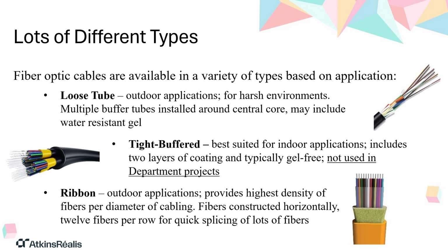Multiple buffer tubes centered around a central strength member, and some will include water resistant gel. Now, before you subscribe to the water resistant gel, check the specifications and preferences of the local maintaining agency, as some agencies are moving away from the inclusion of water resistant gel within cables due to the maintenance nightmare that it has sometimes created.